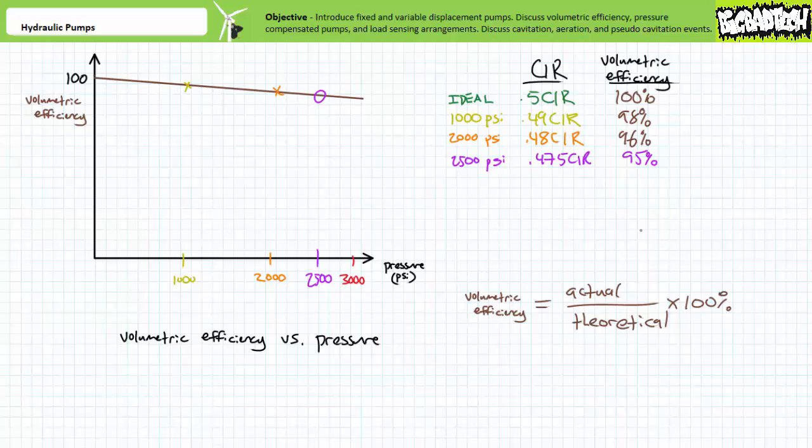Note volumetric efficiency is ordinarily plotted using a nominal rotational speed. The pump manufacturer may also include additional volumetric efficiency charts at other speeds. Pump manufacturers, in addition to a pressure range, may specify minimum and maximum drive speed. Operating the pump outside the recommended speed range may cause excessive wear, or at the very least be extremely mechanically inefficient.